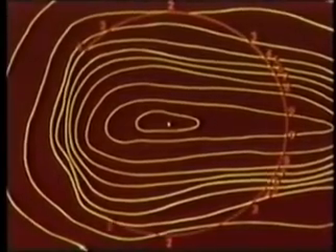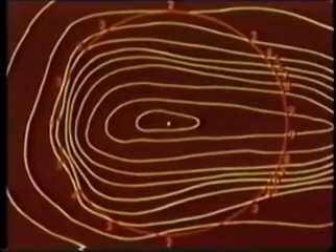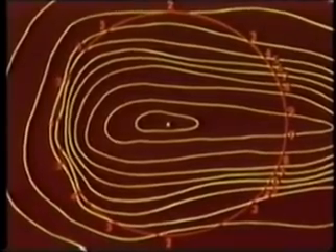It is often more useful to know the shape of the field radiated by the antenna. To achieve this, we obtain field strengths at a fixed radius from the antenna. We now use a vectorial presentation to give each reading a magnitude and direction. To plot this, we use a scale of circles.